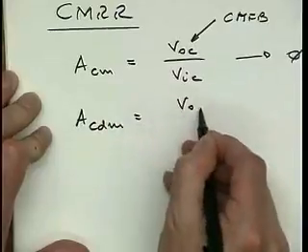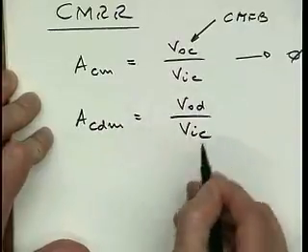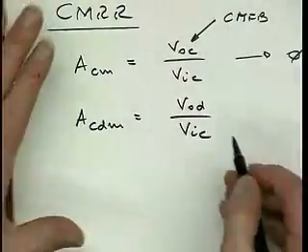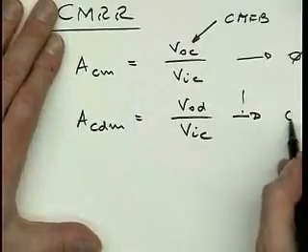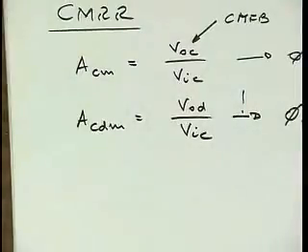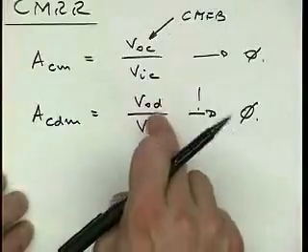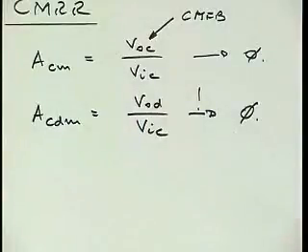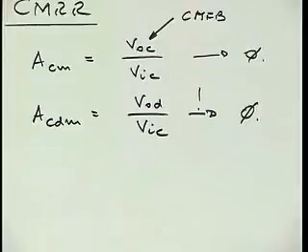That's the output differential voltage over the input common mode voltage. Now this really we want definitely to be small, right? Because we really don't want to generate an output differential. The minute we generate an output differential voltage from our undesired input, the game's over, right? Because that now mixes with the signal. We cannot separate them ever again.